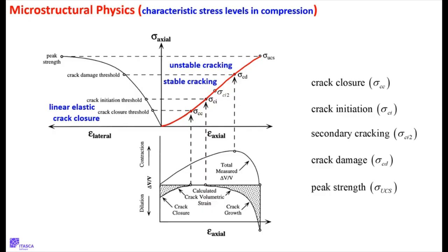Sorry. Okay. And in the granular material, as you start to squeeze it, they rearrange a little bit and you form new contacts until you reach a point where there's pretty much no more new contacts. You've got a tight packing, and then it's just linear for a while. And so there's rearrangement and new contacts forming. When new contacts form, it gets stiffer. It's like you've added new springs in there.